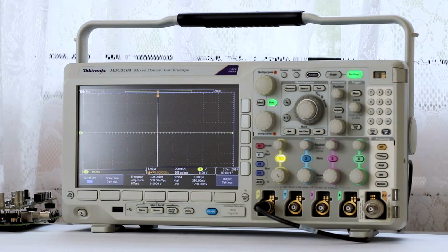Real-time oscilloscopes, such as the MDO3000 instruments, in their simplest mode, digitize all acquired points in a single trigger event. But as we shall see, there are variations in this procedure imposed by the user for specific purposes. To see how all this plays out, first we'll place a signal at an analog channel input, and then see how we can modify the acquisition process.